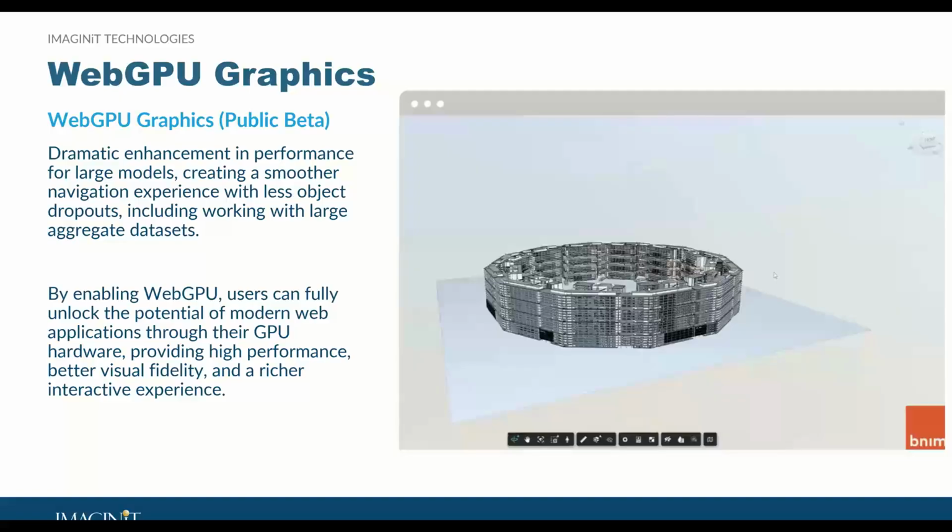Again, that concept in Navisworks, the occlusion, so if it's not visible, it's not needed to be processed, that kind of thing. It helps us with these large data sets when we're having federated models all loaded together. Again, these web GPU-optimized viewers allow them to work more efficiently. And so when we're in the web, just navigating, scrolling, and doing our walkthroughs, measurements, etc., it's going to allow for smoother performance.